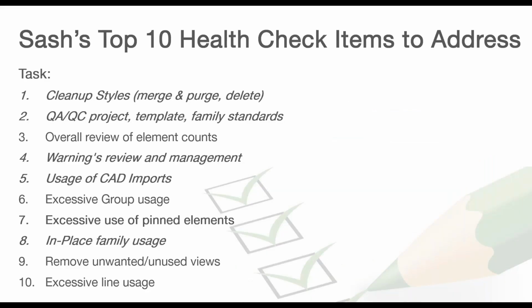And here's my top 10 list of health items to address. And that's just using our 2 products that will be part of the demo today. I have a much longer list than that. But cleaning up styles, doing your QA/QCs, warnings review and management, addressing CAD imports, that's a big one, right? Excessive use of pinned elements, these kinds of things can actually slow your models down. When you have a lot of groups, a lot of pinned elements, or a lot of rooms or volumes that are not enclosed, those kinds of things can really slow down your projects.